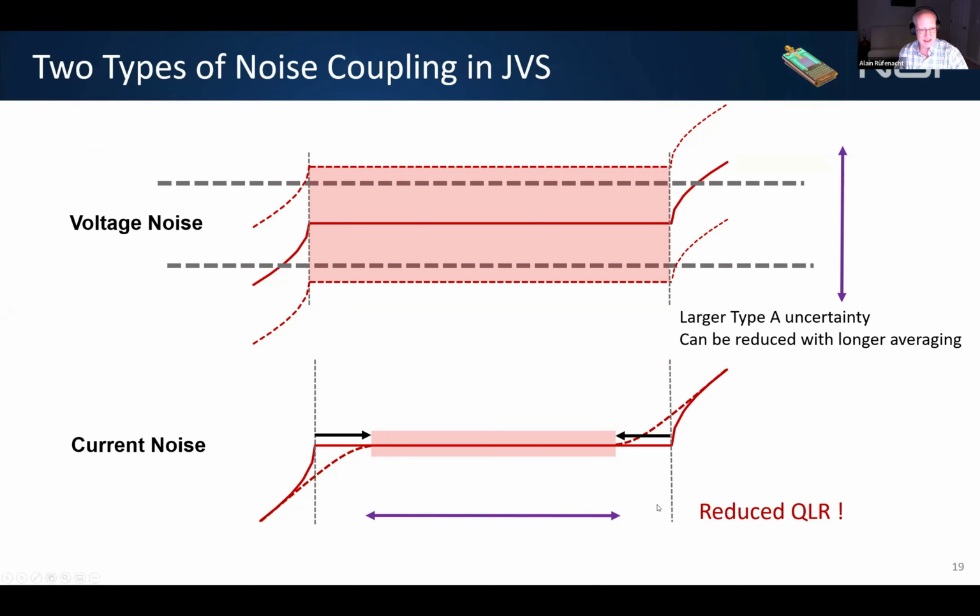So this is another reason when you do your measurements with the system by itself, and then you connect your measurement circuit, could be measuring a voltmeter or Zener or any other devices, that you verify the quantum locking range while doing the measurements. Another good example will be if you measure the quantum locking range, for instance, with a cable balance, because now you have a large apparatus that's actually connected to your JVS array. So these are the things that could happen, and we want to be sure that we remain quantized during the measurements to avoid any surprise.